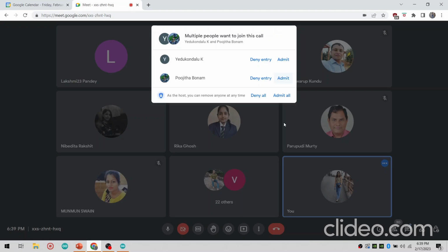Now social sensing in wireless sensor nodes. So social sensing based duty cycle management for monitoring rare events in the wireless sensor network. Duty cycle management means these nodes are not going to be awake for full time. After a particular interval of time, these nodes are going to sleep, and after every frequent interval of time they wake up, sense the information and exchange the information. With the help of this, the energy consumption is going to be reduced.